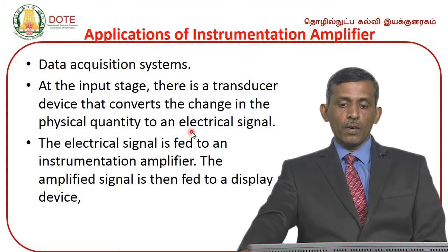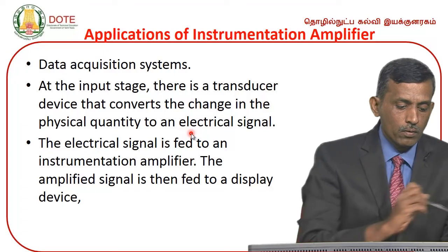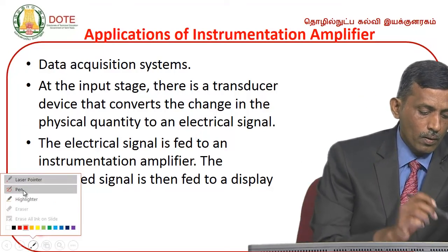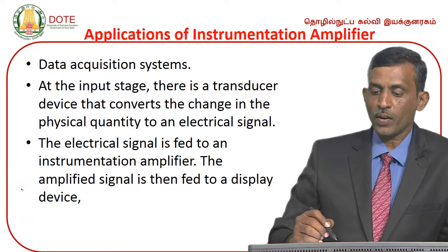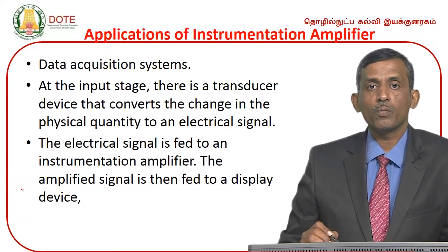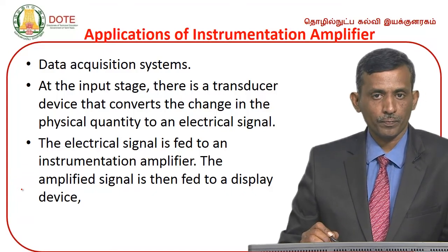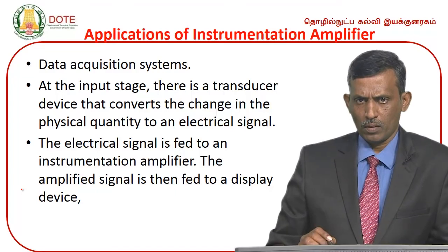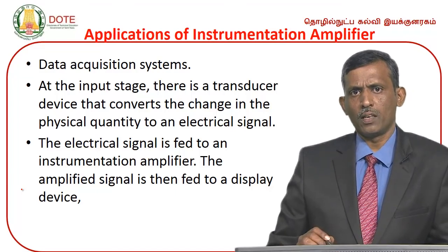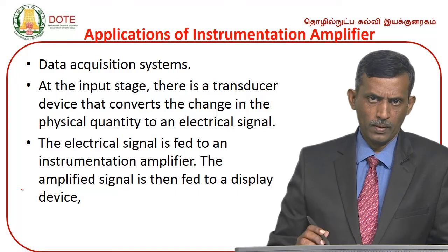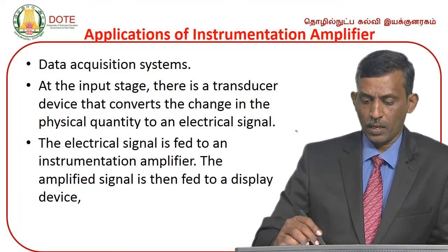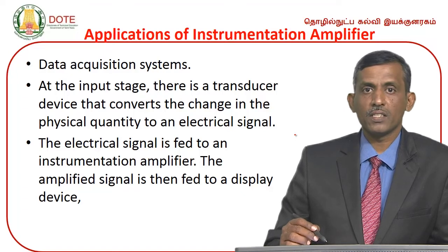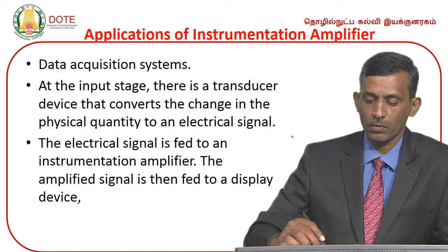See, for example, I can explain one example here. Suppose I am interested to measure the temperature, or I am interested to measure the weight. So basically in instrumentation, the sensor is used in a bridge circuit, Wheatstone bridge circuit, something like this.